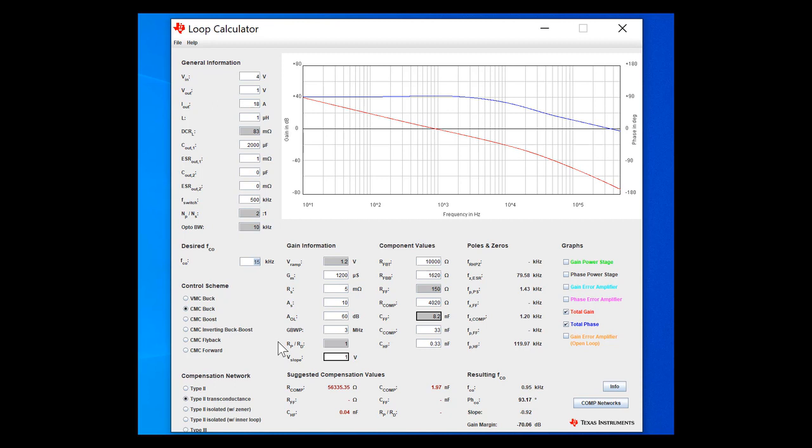you should always be looking at quite a bit lower than the double pole that happens to your frequency response at half the switching frequency. So you want to be a decade lower than that. But sometimes you want to be even a bit lower just to make sure you have a working product just to test out initially. And so I'm going to put about 30 kilohertz here as the starting value.